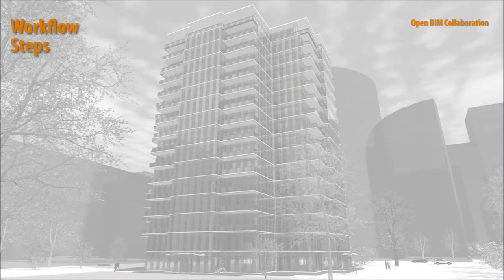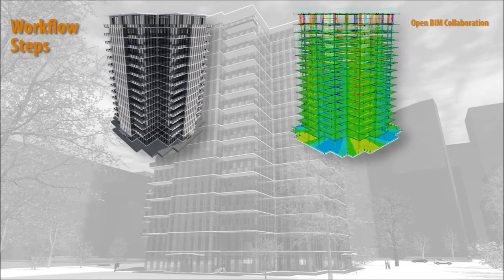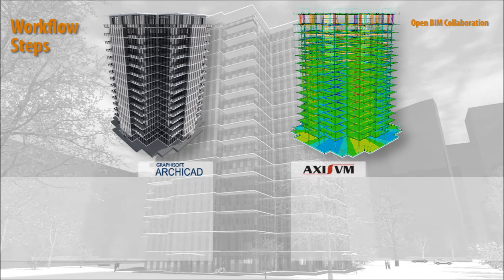First, an overview of the main steps of the Graphisoft ArchiCAD and AxisVM workflow. Let's start with the architectural model. Architects create an initial model version based upon the client's request and the given building site. Architects filter the structural elements by using element classifications, layers, layer combinations, display settings, selection modes, and so on, to prepare the model for export. Of course, the entire project without any filtering could also be exported.